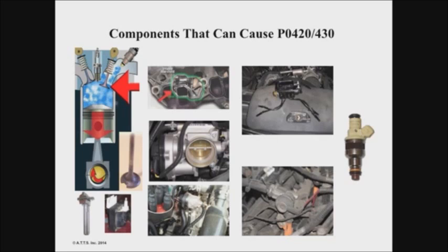People don't look at them. BMW gives it to you nice and hard. If you don't replace those boots on a regular basis, remember the driving machine, well, it's going to burn out not just the coil, it's going to burn the driver, and guess where the driver is? In the $1,200 plus PCM. And yes, you need to program it, and you got to change the coils and boots anyway. So you need to look at it. You need to look at all of those different components there.